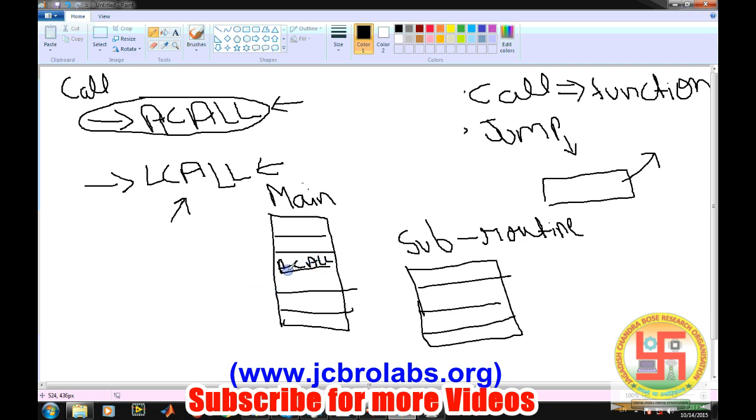When this ACALL instruction is executed by the computer, the content of the program counter will be the next instruction to be executed. Now at this ACALL instruction, control needs to go there. That means this particular address needs to be fed into the program counter. So the current address of the program counter needs to be stored somewhere.